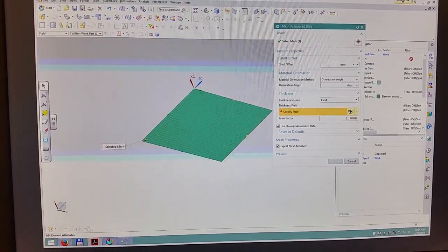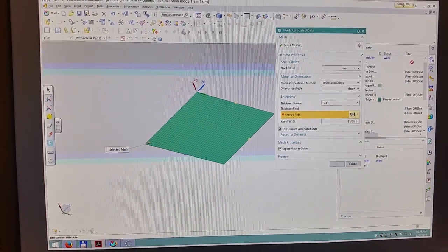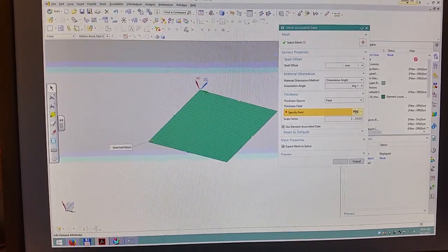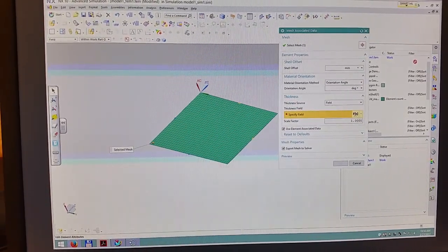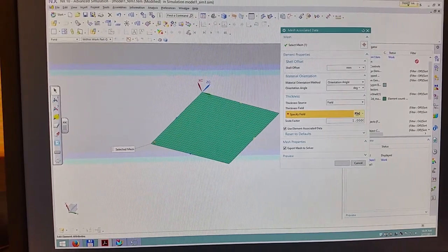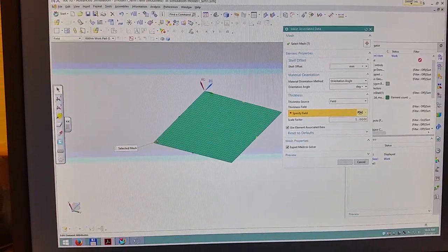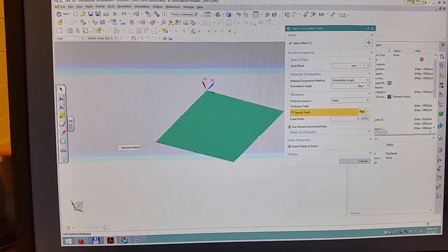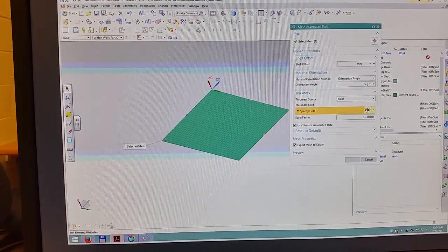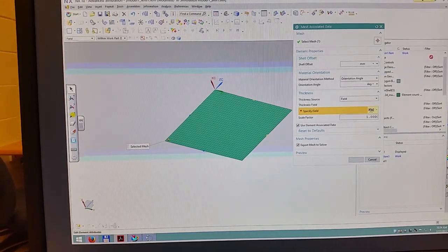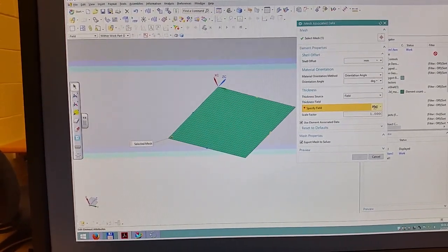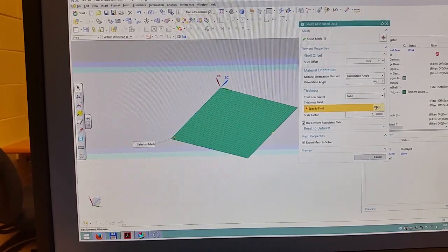So from 1,000 to 3,000 millimeters, I want my thickness to vary linearly. So that when I get to this edge, along the edge, my elements are gonna have a thickness here of 8 millimeters, right? So it's basically gonna be like this. If I look along the side of my part, my thickness is gonna go like this, and then it's gonna expand out, right? That is what it's gonna look like.